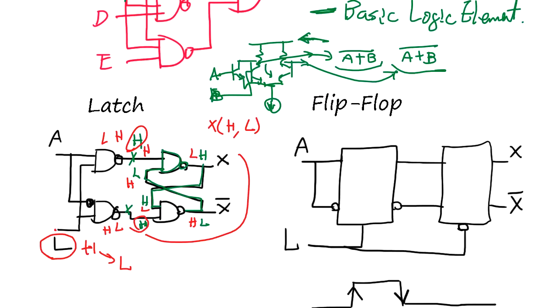It's like a memory, right? So latch is a memory, but constructed by logic. The real memory chip, we describe later, uses a different mechanism. You can't afford to spend so many gates to make just one bit. You need gigabits of memory, so they simplify in a very clever way to have one bit of memory. But this is a logic memory. The memory element made by logic is called a latch.